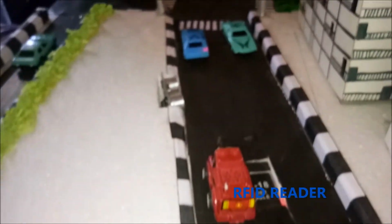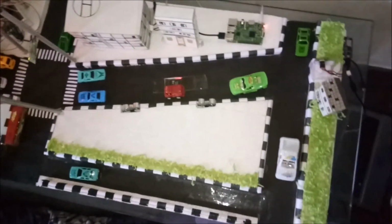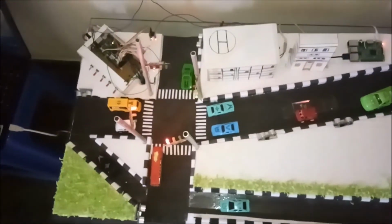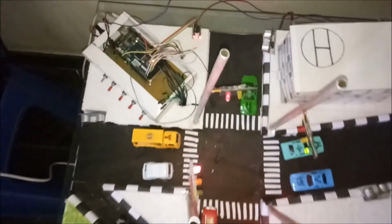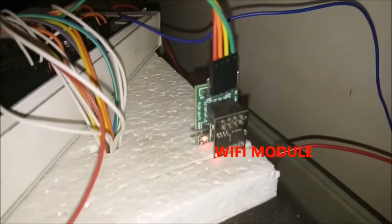An RFID reader is placed on the road surface and a tag is placed in the emergency vehicle. This module directly connects to any microcontroller UART or through an RS232 converter to a PC. The next component is the Wi-Fi module, ESP8266. It is used to communicate with the cloud to upload the data. It has a 32-bit RISC CPU, 64 KB of instruction RAM and 96 KB of data RAM, and 16 GPIO pins.